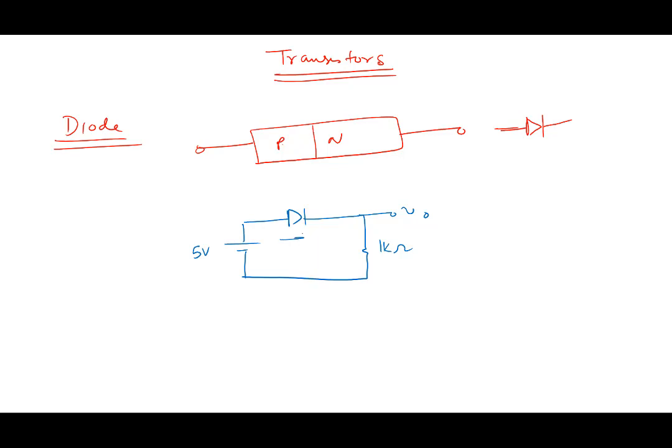With the resistor, I knew it's a voltage divider. But now that I put a diode there, what do I do with the diode? How do I look upon a diode? What is the behavior of a diode? When you see a diode, what is its behavior? It can act as a switch, below the cutoff voltage. No. It will act as open. And in the ideal case, after the cutoff voltage, it can act as a short circuit.